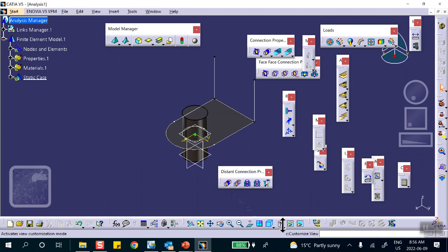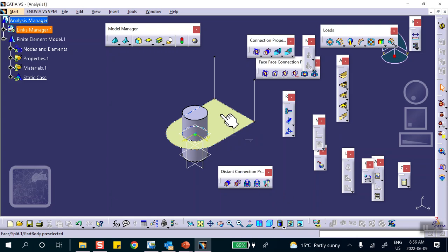Because Catia, by default, if it sees a solid, it's going to mesh it. Let me change the rendering here. There we are. If you say show me the mesh, it will show you the mesh, but it's only that cylindrical object, which I'm not going to bother showing you. Now, to do anything else, beam elements, shell elements, you have to do it yourself. Okay, so let's do the shell first.